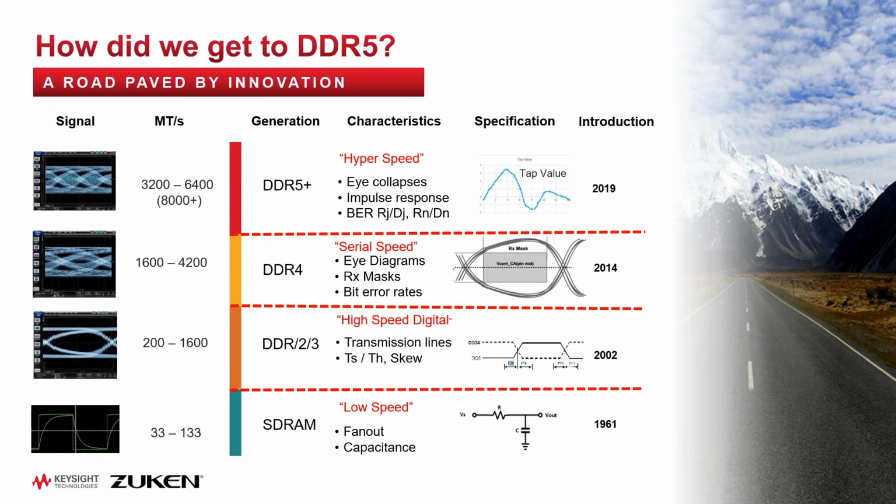The other thing that they did with DDR4 was try to reduce power consumption. They did that by moving to a pseudo open drain as the IO technology. That means that you only draw current when you're driving a 0. And then they also used data bus inversion, which makes sure that if we're only going to draw current during zeros, we minimize the number of zeros across a byte lane. And also, of course, reducing the supply voltage down to 1.2.